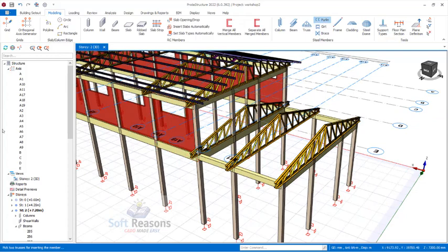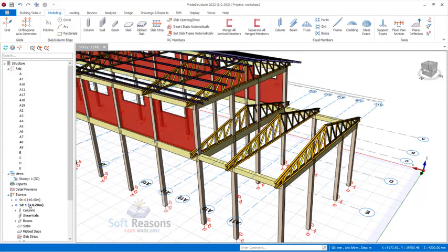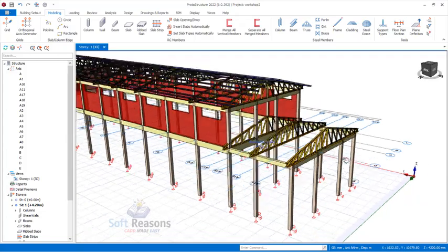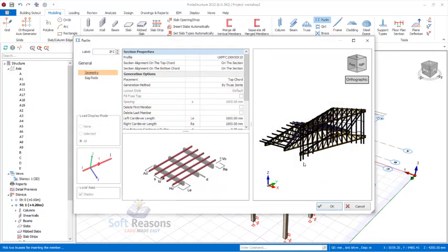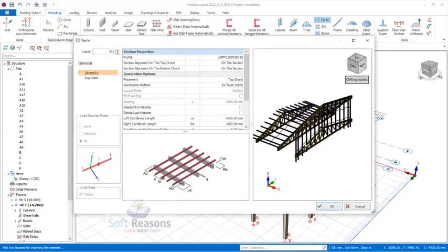Alright, so you have to deselect this particular one just like this before you proceed to pick this. Okay, and then make sure you move the green lines to the story 1. Double click to move the green lines down to the story 1 just like this. So you now pick the purlins, pick this and this. Okay, so we are still having this.